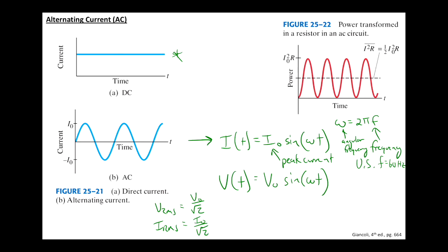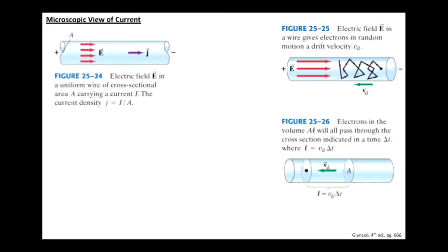If you look at a device that's going to use alternating current, you might see two numbers printed on there. If it just gives you a value for the potential that this device needs or the current that it needs, and it doesn't specify, it's probably the RMS. If it does specify peak, then you know what that is. It could give you both values as well, which is another option. So peak is of interest, RMS is of interest, but average really doesn't do us any good.